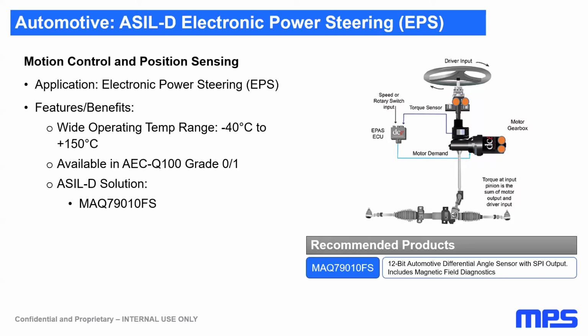But any magnet that's dipole and that you can get that much field. In terms of magnetic field strength at the sensor, one of the variables is the magnet material. So neodymium is the strongest, but the other variables are the magnet size and the air gap between the magnet and the sensor, and it's not difficult to get a ferrite magnet close enough to provide enough field.